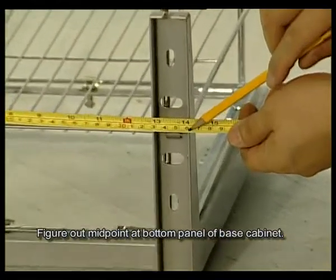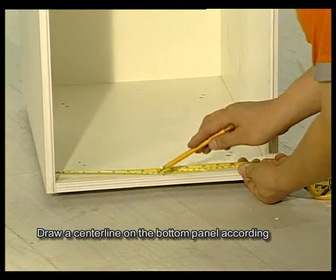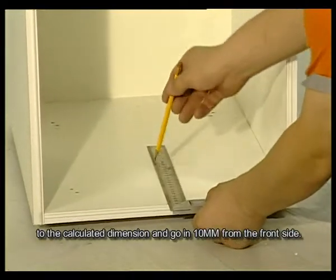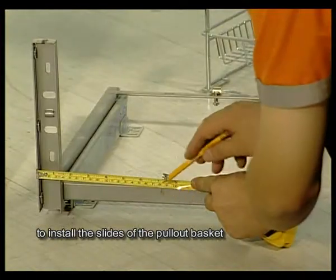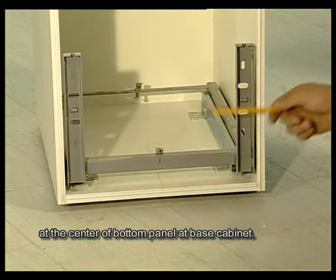Figure out the midpoint at the bottom panel of the base cabinet. Draw a center line on the bottom panel according to the calculated dimension and go in 10 mm from the front side. Draw a positioning line for the front of the slides to install the slides of the pull-out basket at the center of the bottom panel of the base cabinet.